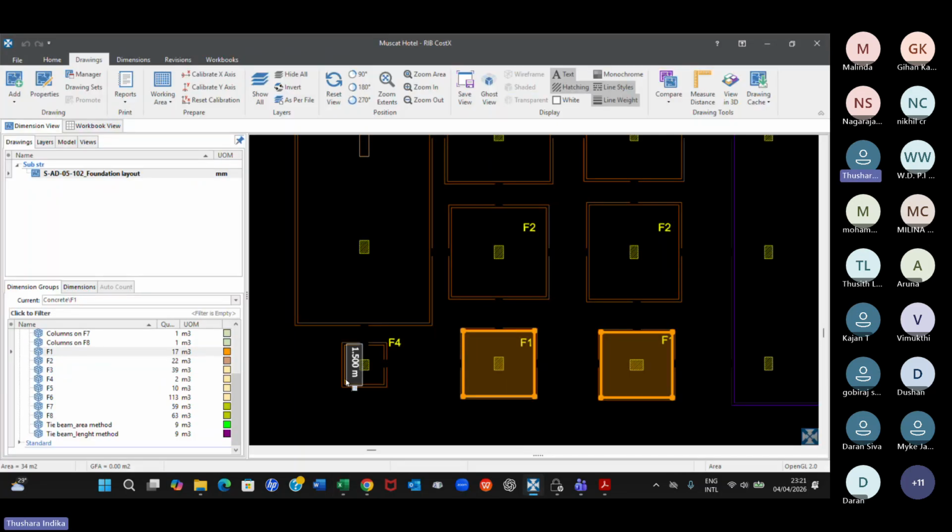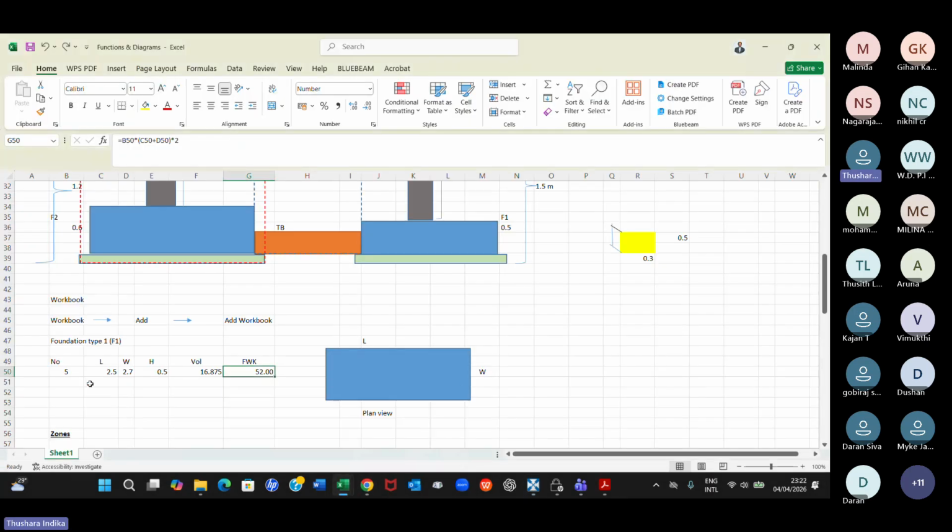I have shown you some of the parameters here. When you say count 1, we understand. Length is 10.4, we know the perimeter. When you say length, height offset, we know. Area is the cross-sectional area or the top plan area. Wall area. What is wall area? Wall area is the formwork area in this case. Now I can say if you put a value here, 1, and you get 10.4, that is the wall area.